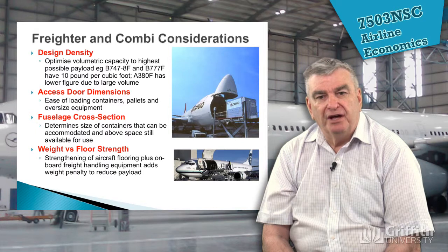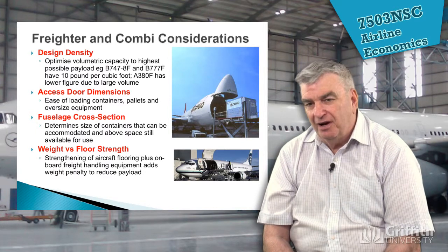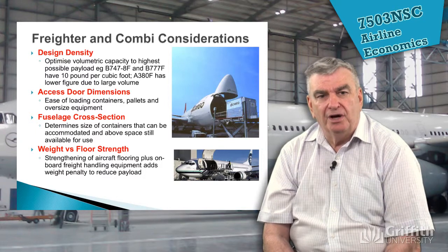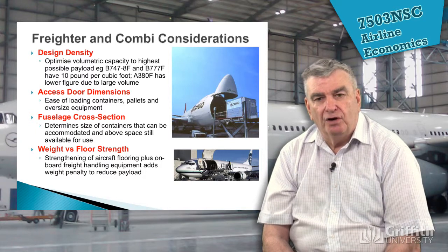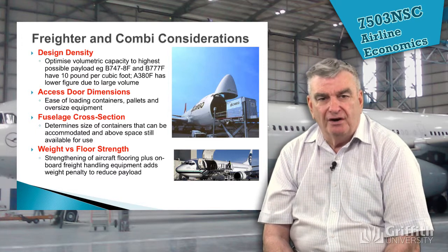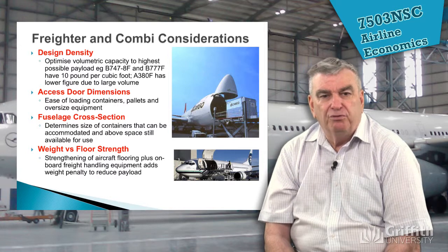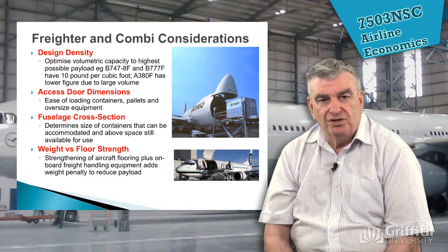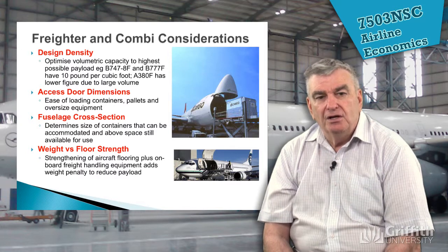We spoke about the fact that very often our freighter aircraft are not built purely for that role, but some are. Some aircraft go through the production line with the F designation, that is, they're built to be freighters, and they have certain characteristics in them straight away. Strengthened floors, for example, where we can raise the nose, as in the diagram here.